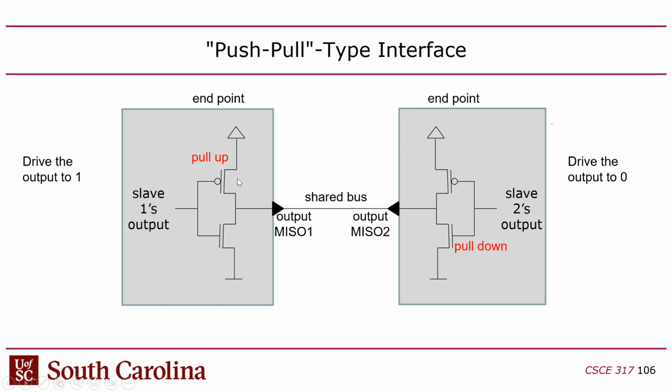They're just shorting their source and drain terminals together. So when you have two of these transistors connected serially through their sources and drains, with VDD and ground on the other sides, this is what essentially gives you an output, because it allows you to turn one or the other of these two transistors on, which will connect the middle point where the two transistors join to either power or ground.